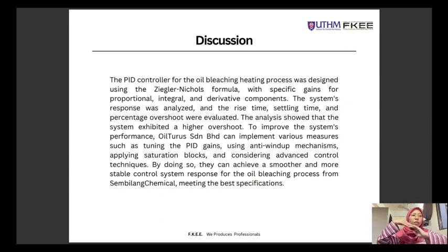The analysis revealed that the rise time TR, which represents the time taken to go from 10% to 90%, is 77.449 seconds, and the settling time required for the output to stay within a 5% band was determined to be 1214.915 seconds, and the overshoot found from this system is 6.67%.